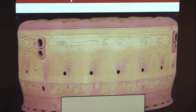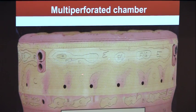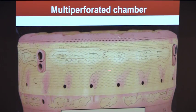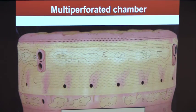That's the picture of a helicopter chamber. Those holes are here, okay? Each of them is a small hole. So in France, we have people, children, drilling holes like this. It's a big job. So, actually, it's done with a machine. But the experience, for example, of Turbomeca is that probably 10 years ago, they changed the process by which they were drilling the hole. They drilled the hole with the same size, same length, but the shape of the hole was slightly different and the engine was not working anymore. Why is it so? It's because the details of every small flow here is important for the flux.